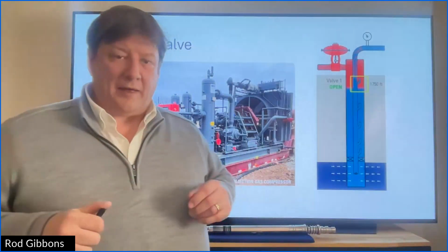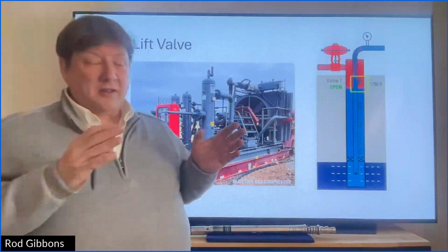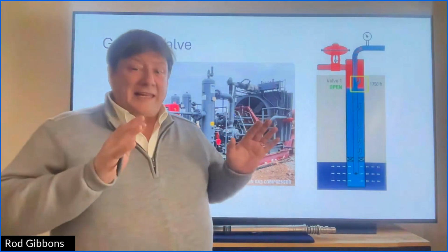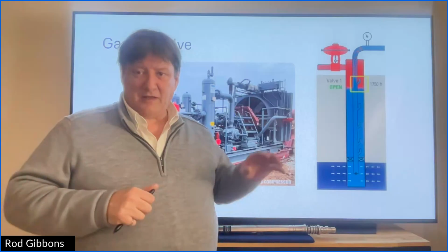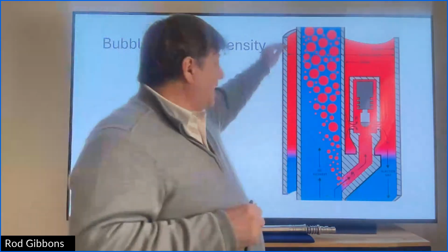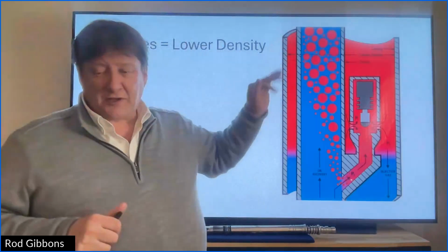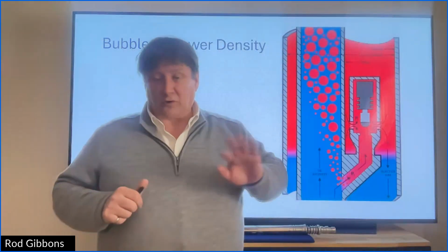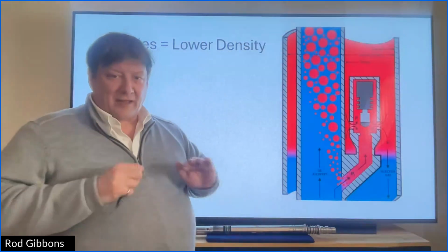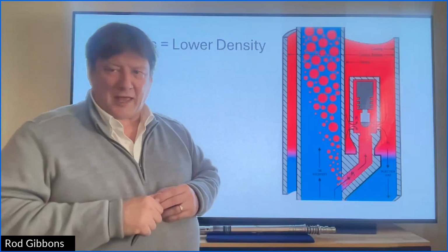So you also want to make sure that after you drill and complete a well, your annulus is clean and doesn't have any dirt or anything in it. So a good question. Yeah, we're going down the entire annulus straight from surface, and that's for offshore, onshore, or subsea. From the tree down to the gas lift valve is basically full of gas in the annulus.